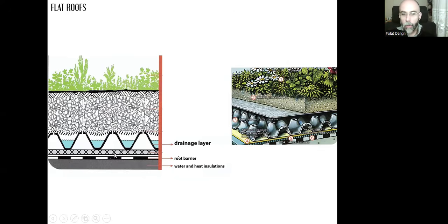It's good for that. And in between, we can place a filter layer because over that, either we place earth, and we don't want the earth to clog these holes or cause problems, or we can place a plant nutrient layer. It's an artificial earth, let's say, where we can have tiny plants.